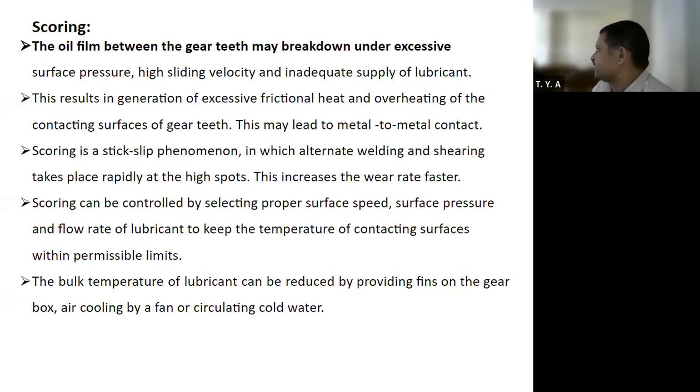When two gears are in contact with each other, there exists sliding motion and rolling motion. The oil film will break because of excessive surface pressure, improper supply of lubricant, and high sliding velocity. These are the three reasons.